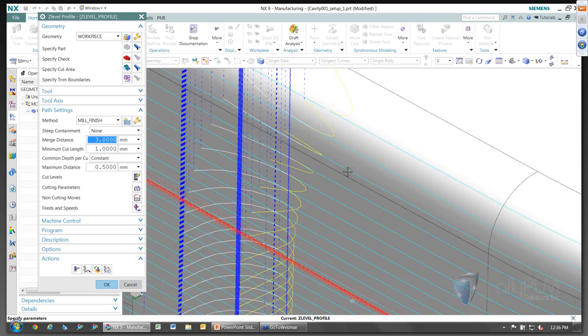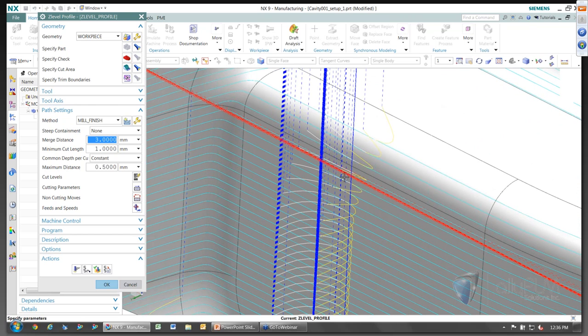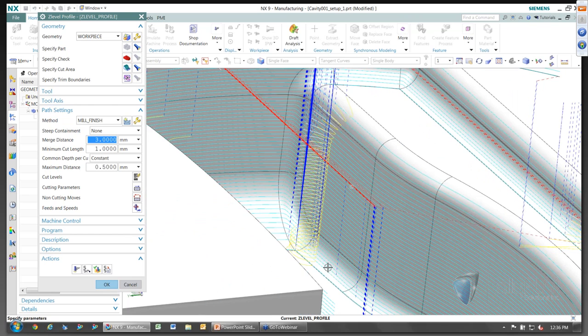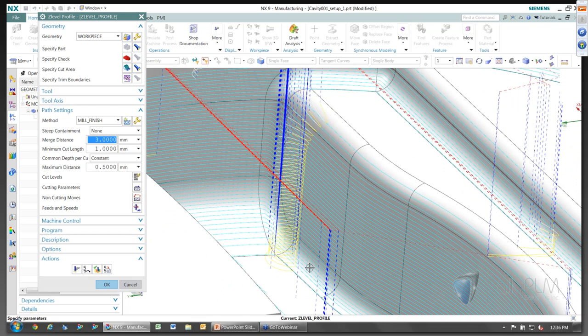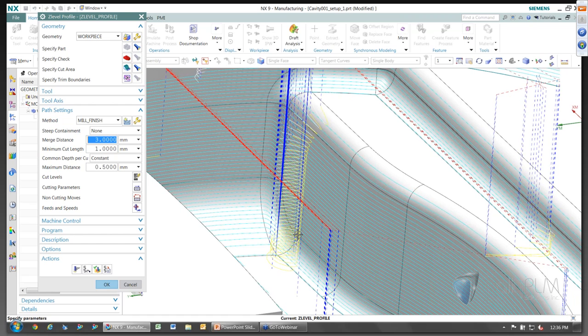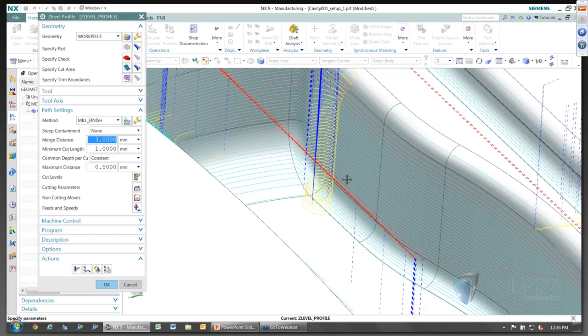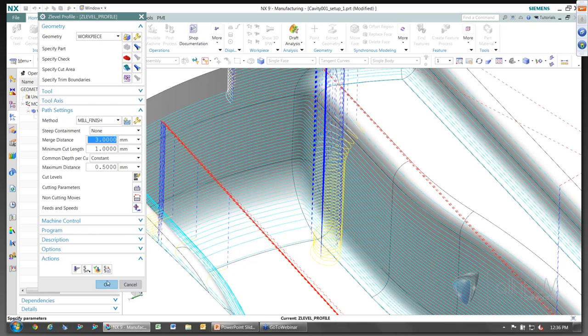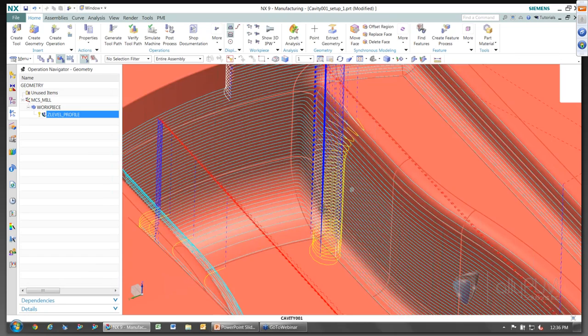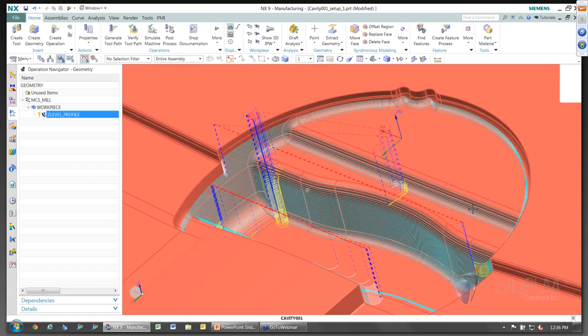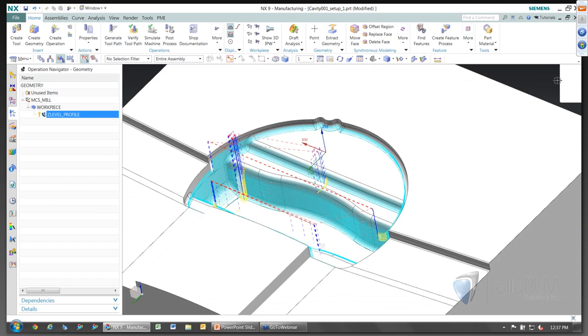So as you can see now, these arc moves are normal to the part surface. That can come in pretty handy if you're trying to get in a tight area where a normal arc-in move wouldn't have enough room to get in there. So these are actually normal to the part surface. It's definitely a nice way to do that, and probably going to give you a better finish as well. Now that we have the toolpath created, as I mentioned before, I'd like to break this up into 3 different toolpaths. I have a short tool, a medium length tool, and then a long tool.